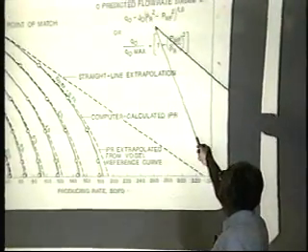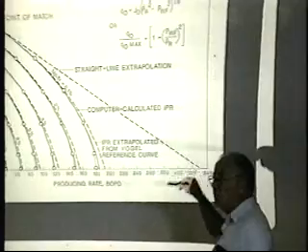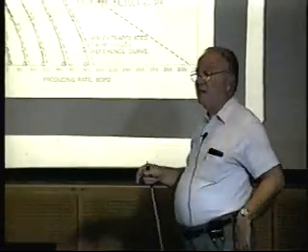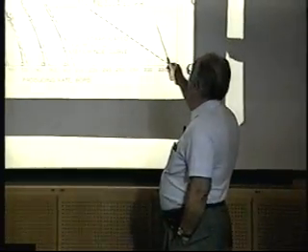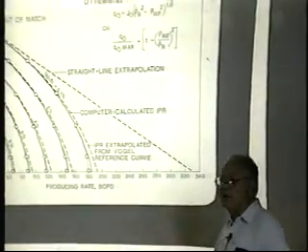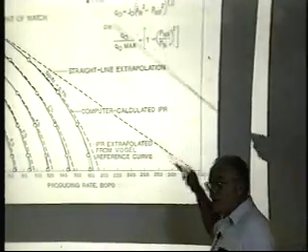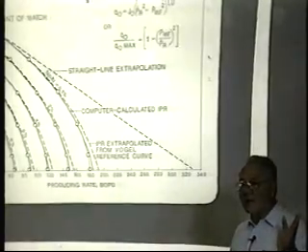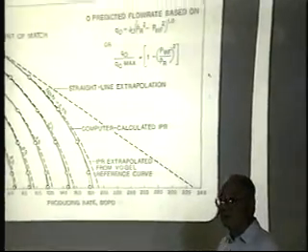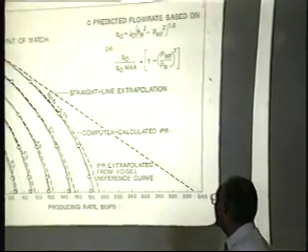This is a form of an oil well inflow performance. The slope of 1 is very close to the Vogel equation. So if you use this or Vogel's, you get about the same results as a production engineer. But as a reservoir engineer, I need to do more. In this form, I dropped the 1 term, and the coefficient becomes 1 for the squared term, and the other coefficient becomes 0. Now I have a back pressure equation where, like I said earlier, the rate's not strongly a function of the level of the flowing pressure that I'm going to choose.